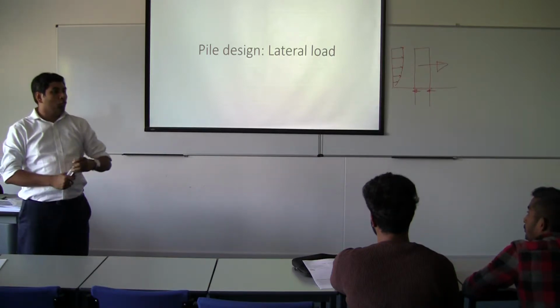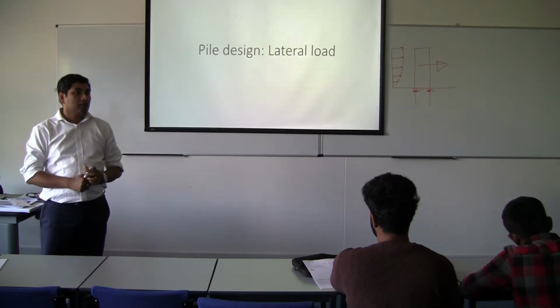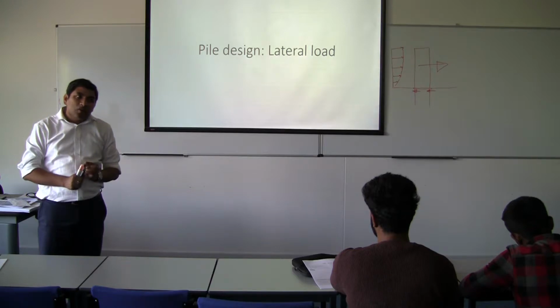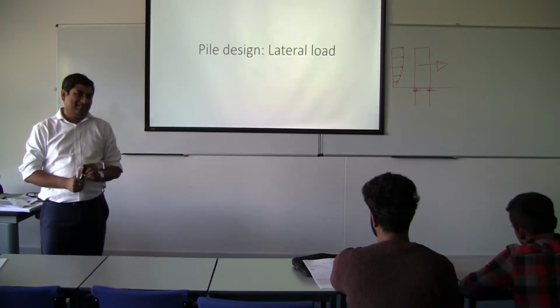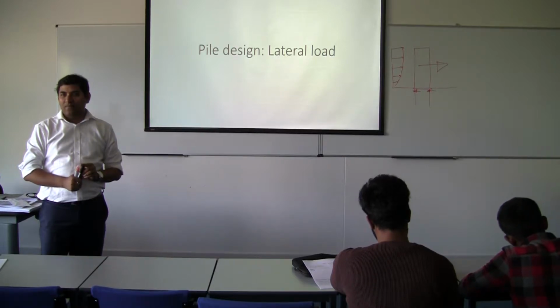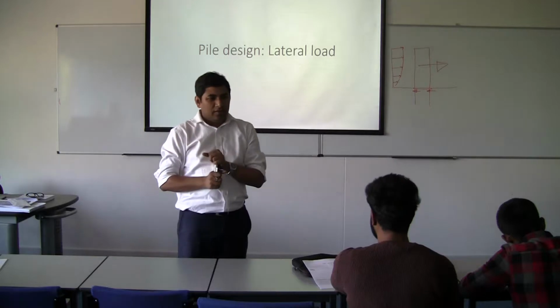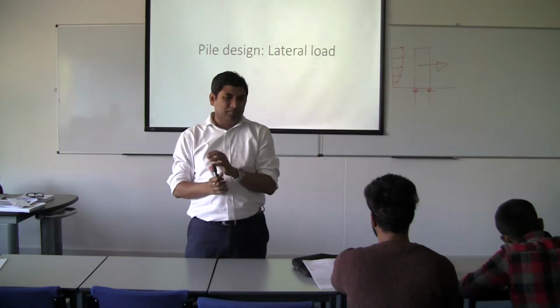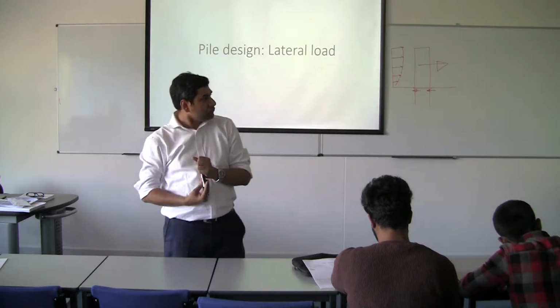Once you move something, they'll give you a snatch load, right? So lateral loads are inevitable. And if you have lateral loads, there's a tendency to put piles. If the lateral load is medium to high, there's a tendency that you have to go for piles for our long-term sustainable solutions, right?